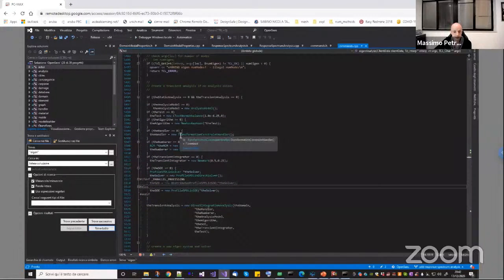Another example is the transformation handler. As I told you in a previous webinar, if you have a very complex model and you have many overlapping constraints, it may happen that the transformation method is not going to work. So in my case, I typically use the penalty method.